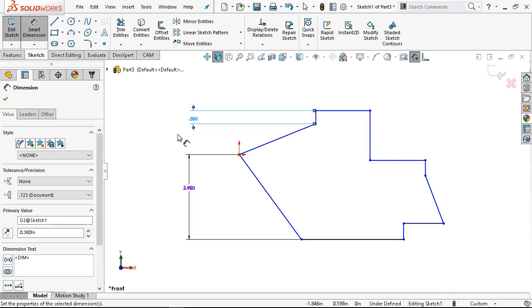All right, so maybe there's 5 of these pieces stacked on top of each other, that whatever they do, when I get to the last one, my mating part is at a decimal plus or minus 5, but I've accumulated that 5 thousandths, and all of a sudden all 10 parts don't fit into that piece. All right, so those are considerations as we go forward.